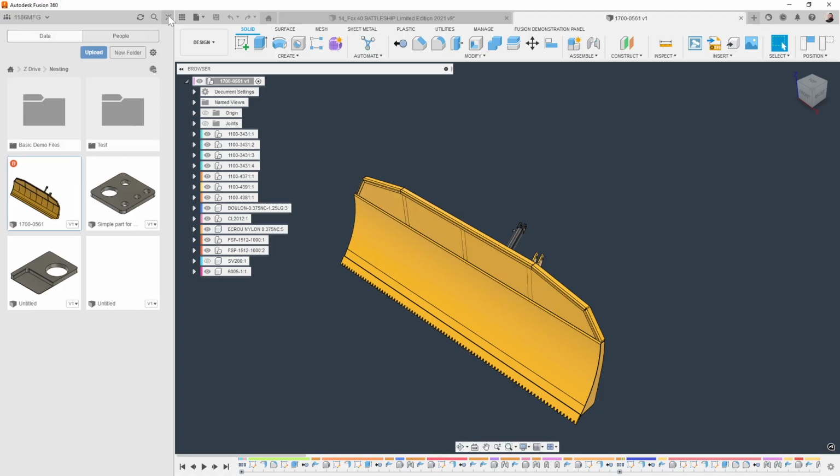It's not sheet metal where you're bending it, but would manufacturing models or nests let you take that built furniture assembly and lay it out nested to, say, put it on a router or water jet? And it kind of does that. So it also includes some of the bent materials. As long as you have flat patterns made for your sheet metal, they should flatten out in here.